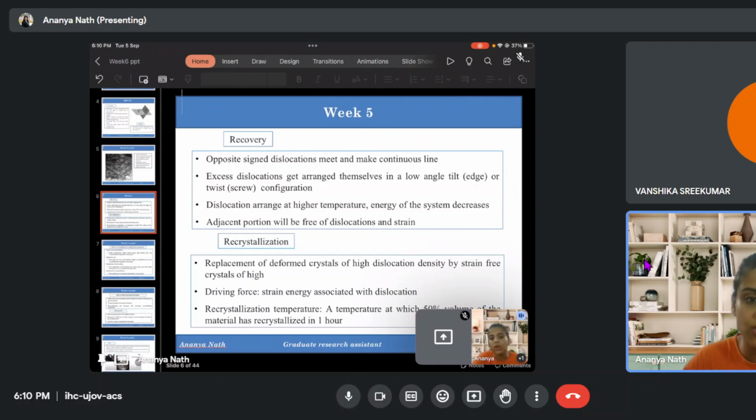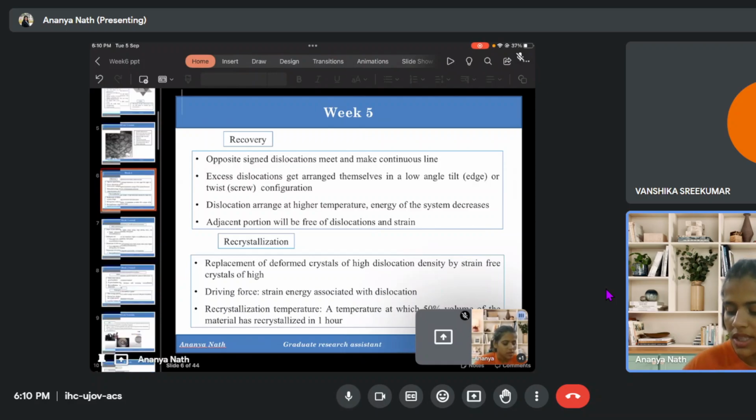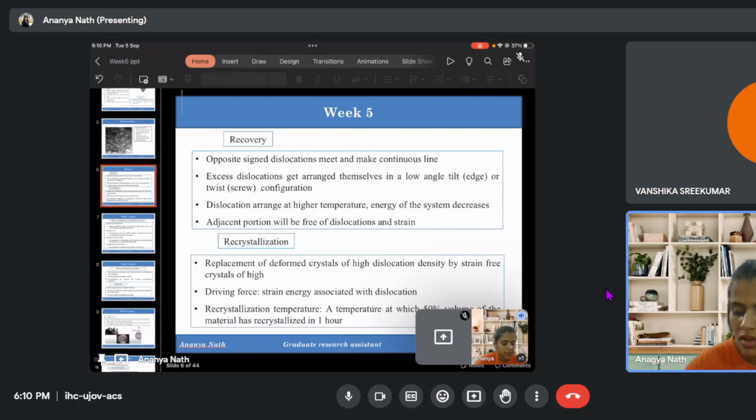The grain will have a definite type of crystallization, meaning the unit cells and lattices are arranged in a particular manner in a particular direction, and that grain is located somewhere inside the material, having some particular crystallization but not containing any dislocation inside it. So this is how we were taught.